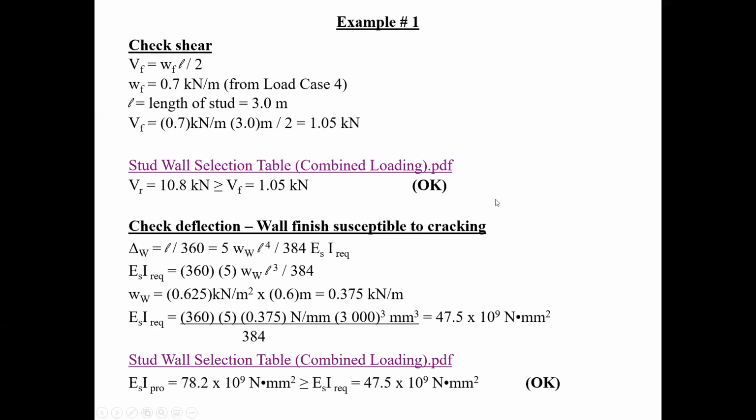78.2, and therefore 78.2 is greater than 45, and therefore you can see that this deflection would be way less than L over 360, so it's way stiff enough. And I believe you have to check bearing, of course, all the time.